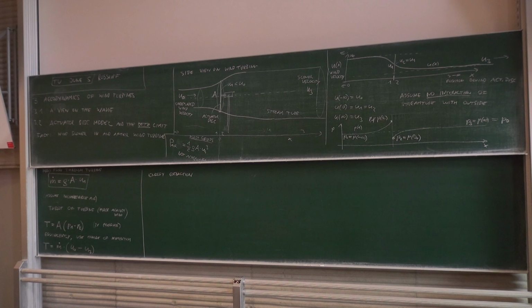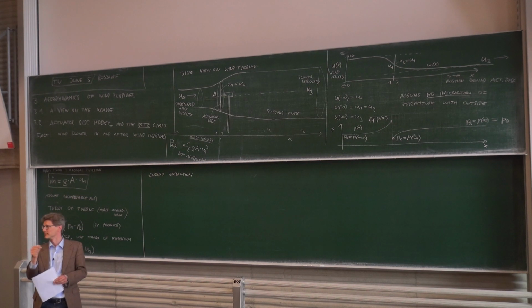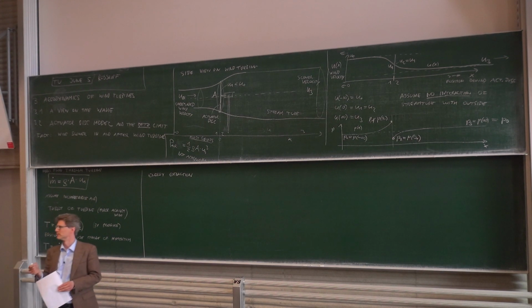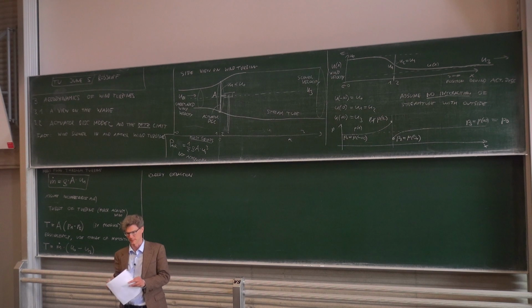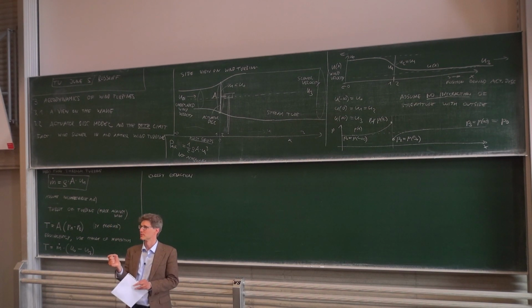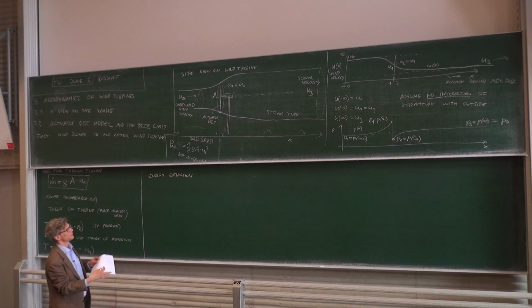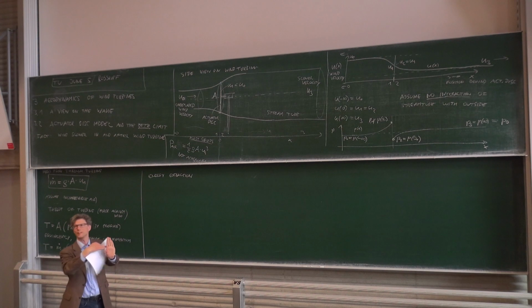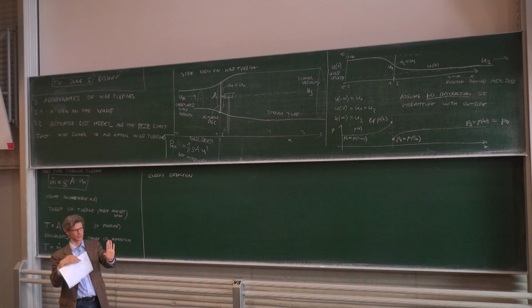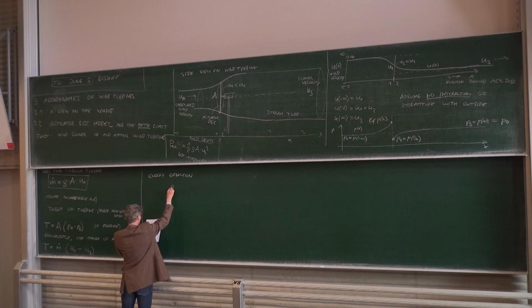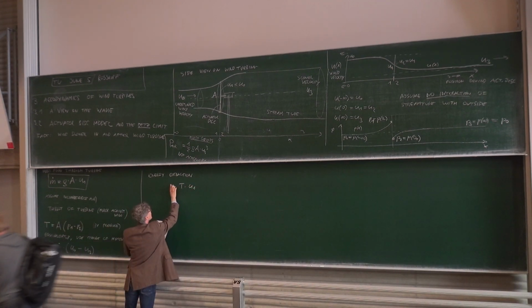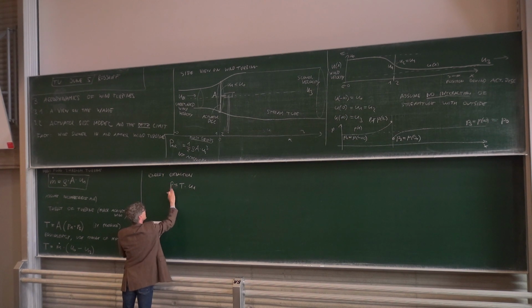So the first one is what we do: we have a force that's acting on air that's flowing through our disk with a speed u1. And power is actually force times speed. We have not used that yet, but force times speed is power. So here we have a force, and we exert this force on air which flows through our disk with speed u1. And because we slow it down, we will extract energy from it. So one way is to just say the power is equal to the thrust times u1.